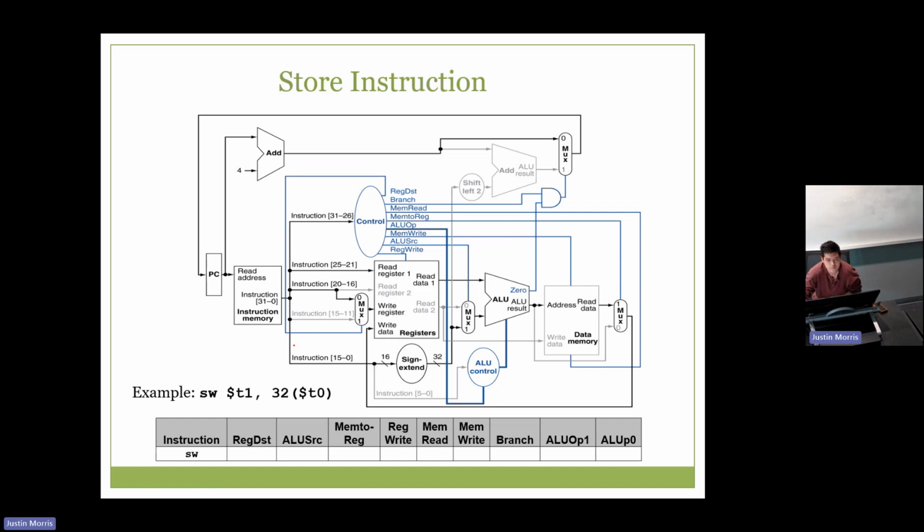It stays in the data memory, right? We're not writing anything in the register file, right? Does it matter if this is 0 or 1 then? It gives me more flexibility to make a more efficient circuit. Okay. ALU source. One. Needs to be 1. I need that sign extended immediate.